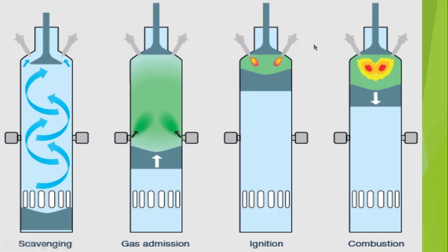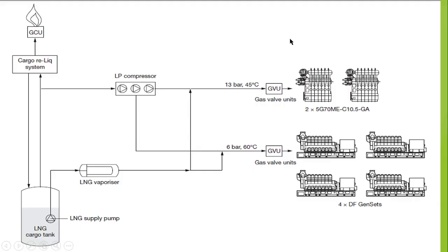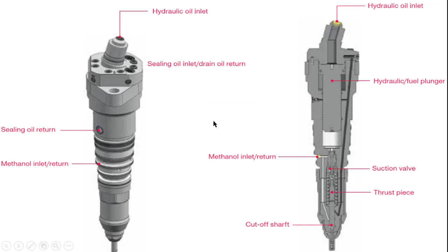Okay, this one will be explained in detail in the upcoming video. Basically it's almost the same as the fuel injector, but the amount of fuel being injected is very small, and this MBIV concept is equivalent to the FBIV, like methanol, but we will see the difference in the upcoming video. For the time being, you should know that the main purpose of this micro booster injection valve is to inject fuel in a sufficient amount to reach a combustion temperature high enough for auto ignition.